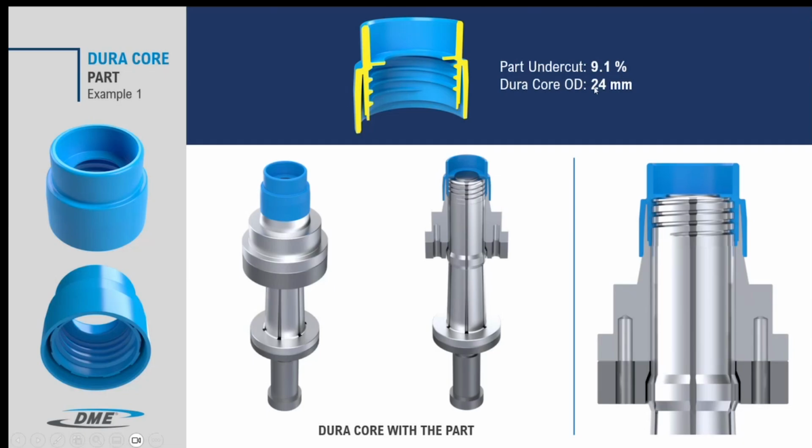And you can see another advantage, it can handle small nearby profile easily. Also, cooling can be provided very close to the part, so the heat transfer is better and this gives faster cooling and reduces the cycle time. Overall, the DuraCore is a simple, effective and reliable solution for this application.